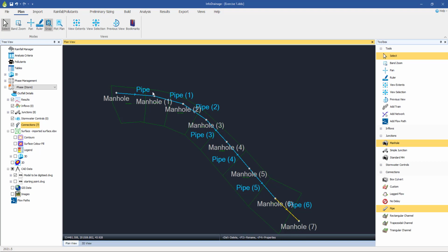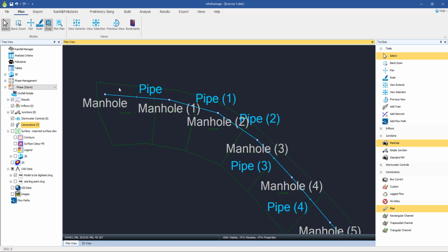At this stage, I'm going to create the 3rd of the building blocks. I'm going to create these areas. Now, what we would do in reality is it would be some skill and judgment from the hydraulic modelers. But what you're essentially trying to do is to say, okay, if rainfall lands in this area, anywhere within this polygon, I assume that it's going to drain to this manhole. So that's the judgment that you're making. InfoDrainage can't help you with that. That's purely your assessment to make, to say, I think this area is going to drain to this manhole. Okay, and that's what we're going to do.